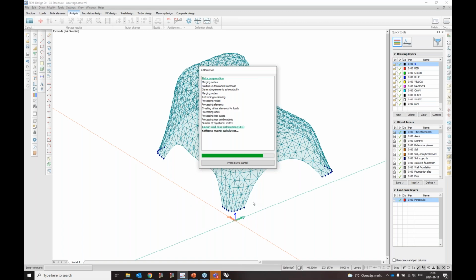So it's a bit of a trial and error process, I think, but you have to really think about the meshing when you work with this type of structure. You also, of course, have to think about instabilities in shell structures like this. So I would recommend running a stability analysis on this to look for buckling phenomena.